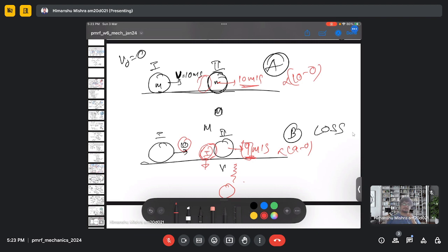Yeah, but in the car, for understanding purposes, I can remove all this part to model my problem. Okay, there is some generation of energy which anyhow created a force which balances all the opposite forces. This is my thing: when it is moving at 30 meter per second, the same friction is acting, because friction is not changing with velocity. So at 60 meter per second also, friction is the same.